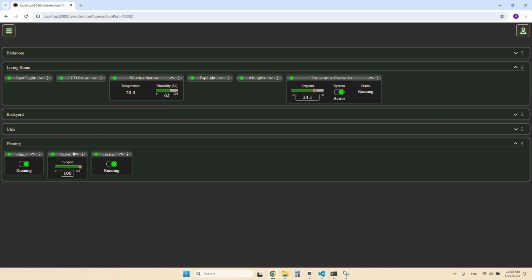The current temperature is way below the set point, so the valve is fully open, but we are getting closer. And the valve position is reduced automatically to keep the temperature as desired. Perfect, the temperature stabilized approximately where we want it. Let's see what happens if I decrease the set point. The valve got shut, the temperature is falling.